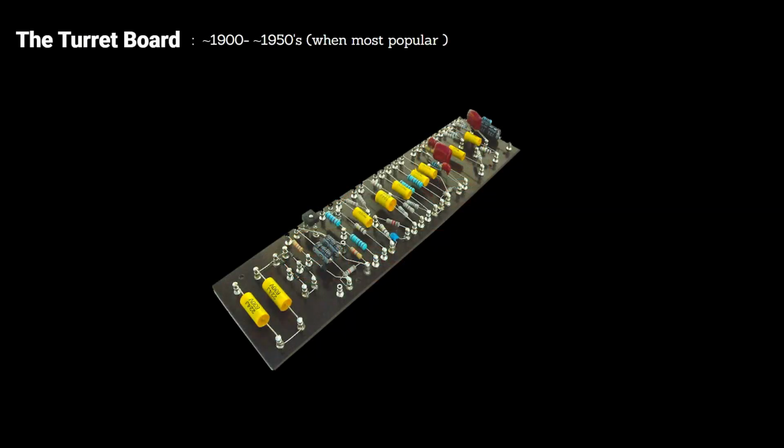So what you see in front of you now is a turret board. These were commonly used in electronic manufacturing for the first half of the 20th century. They were also used in military electronics during World War II and also used in applications like audio equipment, guitar amplifiers and power supplies, etc. Their popularity reduced with the rise of breadboards and printed circuit boards later on, which also allowed for quicker and cheaper manufacturing. So turret boards are still used today in some applications, and actually the fact that they're point-to-point wiring is particularly good with high frequencies or high power dissipation.